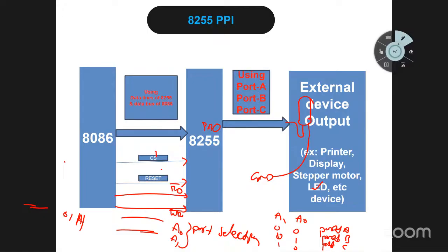I have drawn the block diagram. But draw with the 8086 pin diagram in place of the 8086. All pins are not needed, just the data bus D0 to D7 data lines. Then the 8255 you can use. Then the circuit diagram for this LED connection: in the 8086 place you can draw the pin diagram, and in the 8255 place the pin diagram.